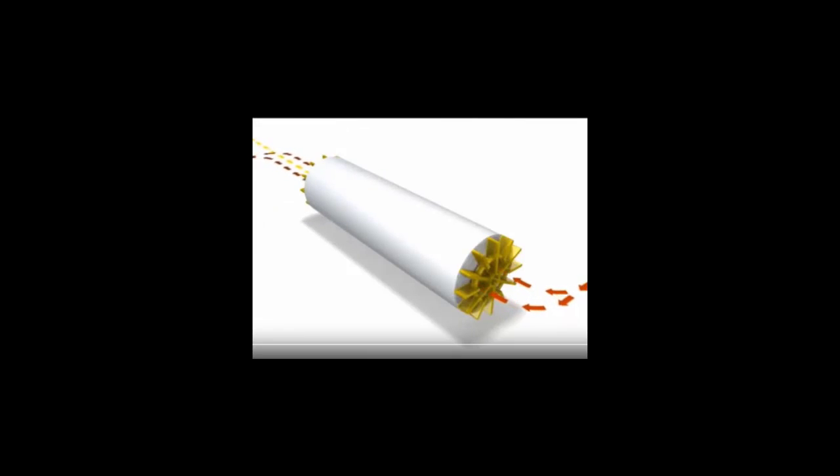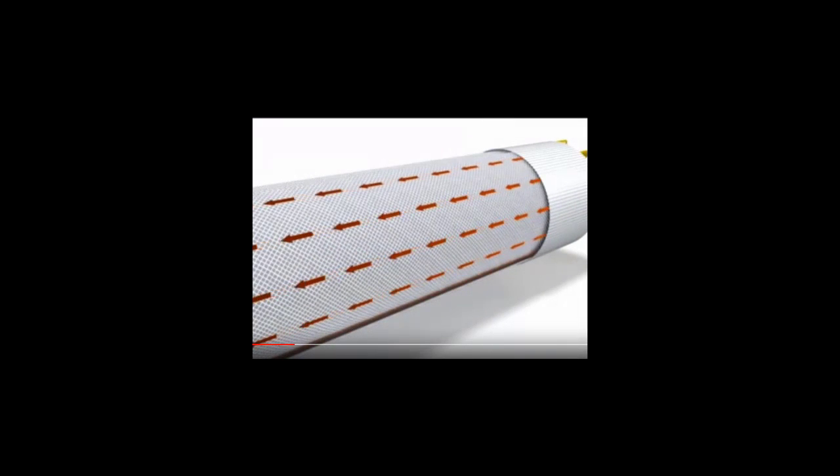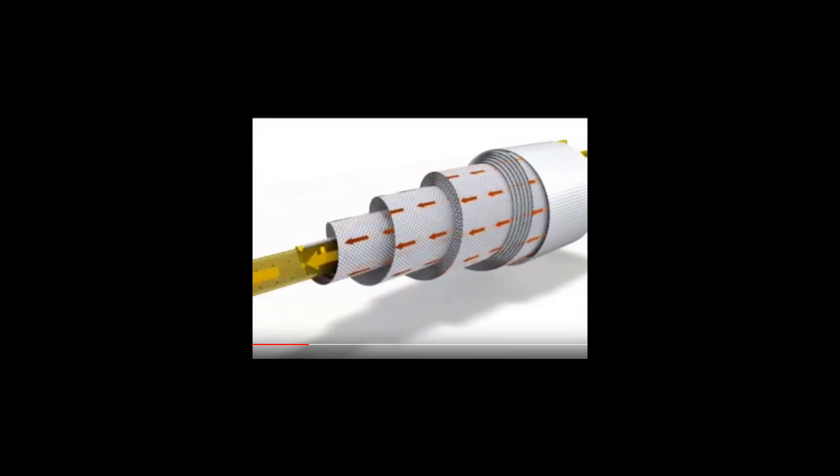Feed enters at one circular end of the spiral membrane and travels down the membrane here, illustrated by the red arrows. Permeate, illustrated by the yellow arrows, and retentate, illustrated by the dark red arrows, leave at the other end of the spiral membrane. As the feed travels down the spiral, it becomes more concentrated, illustrated by the increasingly deep red color of the arrows. This concentration effect is due to the fact that the transmembrane pressure, that is, the difference in pressure between the feed and the permeate side, induces a flow of permeate through the membrane layer.